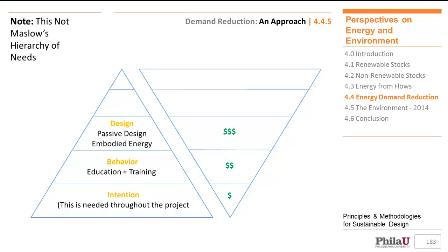And so the next level is actually building a new building. Buildings are static in the sense that they're not moving, and therefore you get a one-time shot at getting energy efficiency. So the orientation of the building, the location of windows, the disposition of spaces, all of those things which we're going to cover in the second half play a large role in the long-term energy efficiency of a project. And really it's only something that can be captured once. So we like to think that that's something that will obviously require more energy and more dollars. It's something that's pretty critical.